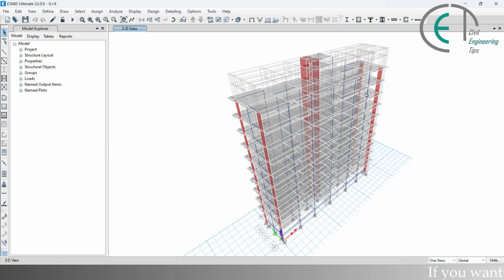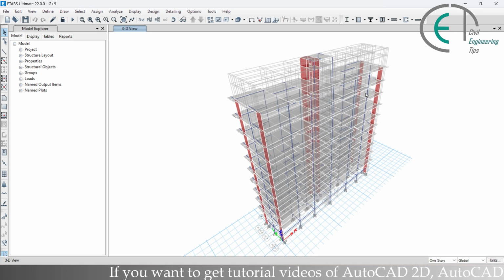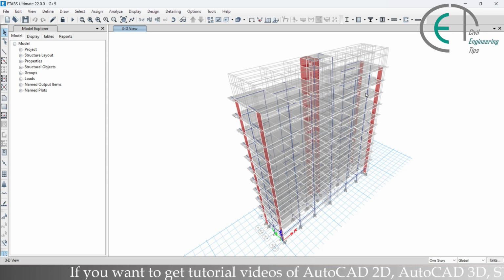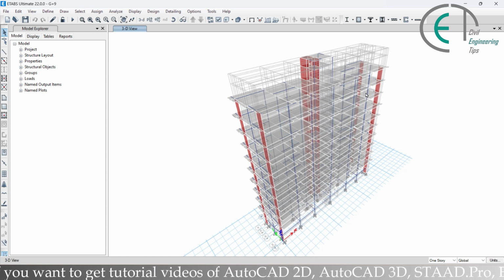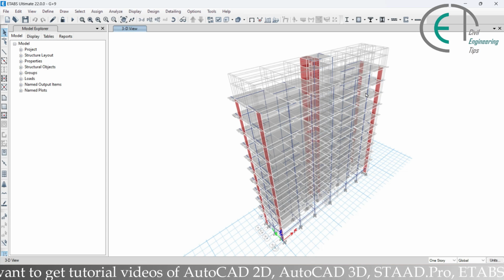In today's video, I'm going to discuss how to unlock a model, or why to unlock a model. After you complete the modeling, you apply loads. Then we go for the analysis and we observe the output. What is the result? If we see that our output is not matching our requirement or there are some complex results, then we change the section size or we can modify the loads.